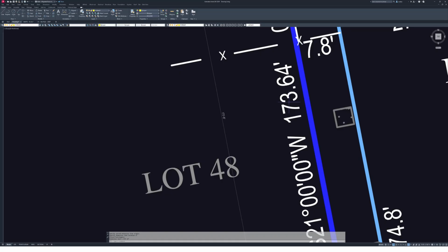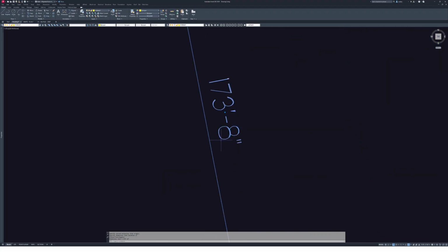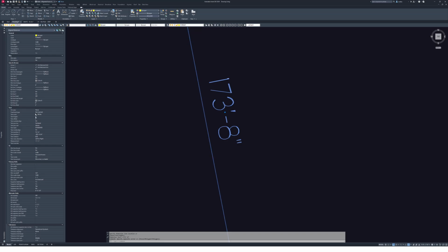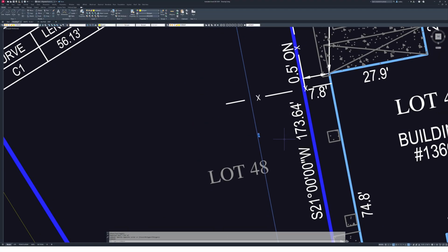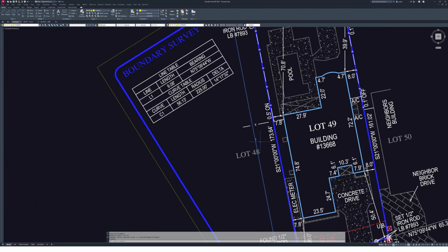Do the quick conversion on the calculator. 173.64 feet equals 173 feet 7 and 11/16 inches. So this is, let's look at our rounding factor. This is going down to an eighth. If I change the dimension round off, it's still coming right at an eighth. So we're off by, what is that, 5/16 of an inch over this whole thing.